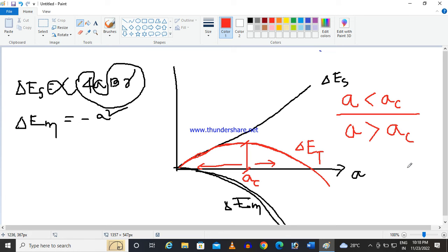That means, here one important thing, if there is a crack in the structure, in the pipe or in the vessel, which is lesser than the critical crack size, then what will happen? It will not propagate. Finally, it will create some leak. The fracture will not take place. But if the crack size is greater than the critical crack size, then catastrophic failure will happen, and it will cause the brittle fracture.